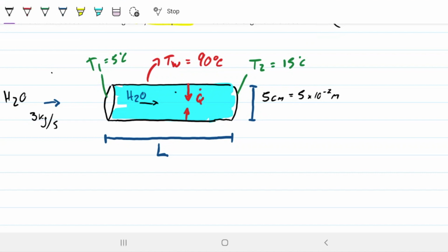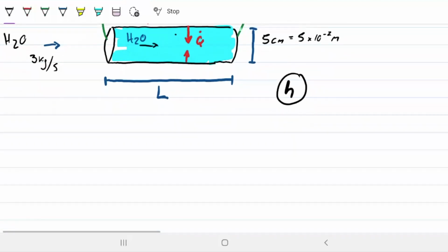There's just one slight problem, which is your old friend convective coefficient. Because we're going to have to use that eventually when you use Newton's law of cooling. So we might as well start by finding h, because we're going to have to. It's going to be the toughest thing in the problem. I'm looking at table A9 this time. So this is in your book. It's also on the sheet that I gave you guys. And if I'm not mistaken, it's also on the lecture slides from the convener. So let's go ahead and plug these guys in.